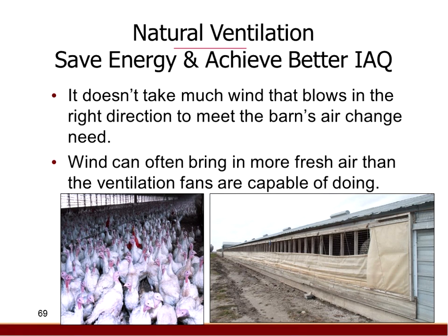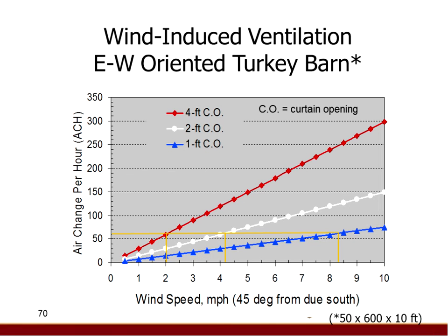In some areas, I can get good ventilation with natural ventilation. It doesn't take a whole lot of wind sometimes to get good air exchange. Now, I won't have the velocity, but I may get the air exchange. So it's capable of bringing fresh air in. So, spring, late spring, early fall, this may be adequate. One of the issues sometimes is to make sure my roof is insulated, because sometimes the sun on this roof will actually provide radiant heat down into the building. So we need to insulate that roof to actually help with cooling in some cases.